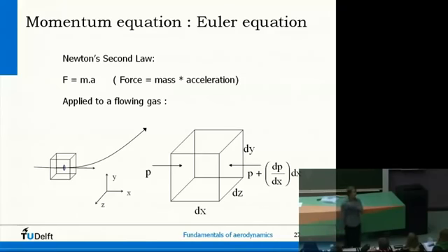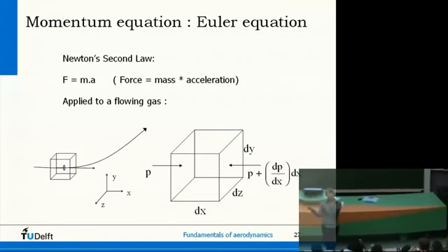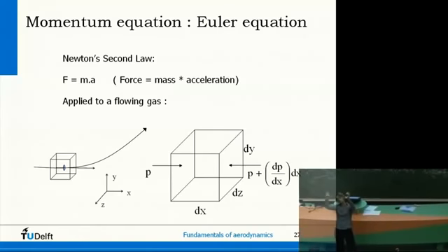Are there any other forces? If you imagine this flow being just somewhere in a room, what other forces are there? Gravity, yes. Gravity, of course. What we'll do is say, okay, it's flowing horizontally, and we will not assume gravity having a major influence. And this is really true for the type of flows we're interested in, around aircraft or so. If you have a bucket of water and you make a hole in it, of course gravity is the driving force of your bucket of water emptying. But in our type of flows, pressure is the main driving force. So we will neglect gravity forces.